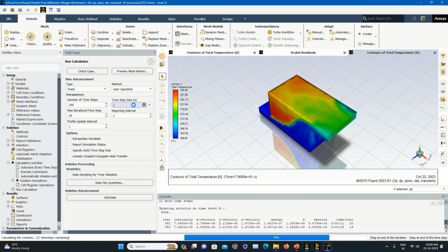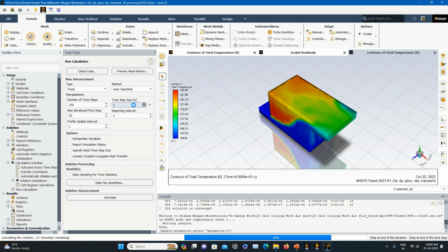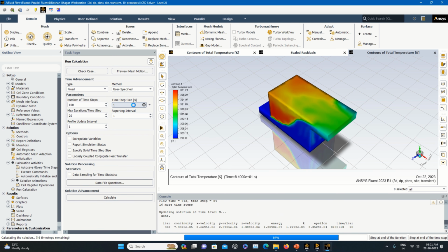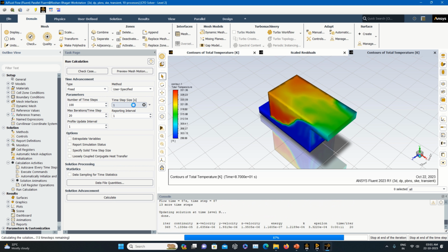But definitely you might be looking for a mesh which is somewhat finer, so as to have a more accurate result than the mesh which you have selected. This is all selected just to reduce the time required for the simulation. Now we come to know the simulation is going in the right way. We can go back to the workbench window and open the mesh again, modify the mesh size, and update the project.